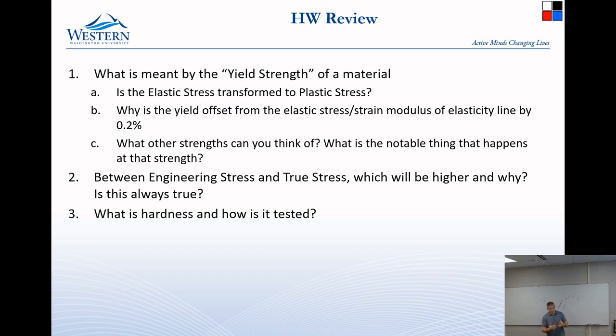So anyway, the next thing I had to do was ask, is it hardened on the outside? Because a lot of times something like that would be hardened on the outside. They didn't know, so I picked up a file and ran it across sideways on edge. And I could scratch it. Because I could scratch it with a file, I know that it's not hardened. That matters, because if it's not hardened, then I can turn it on a lathe. If it is hardened, then I have to use a grinder to cut it. Unfortunately it was not hardened, so I was able to do it.